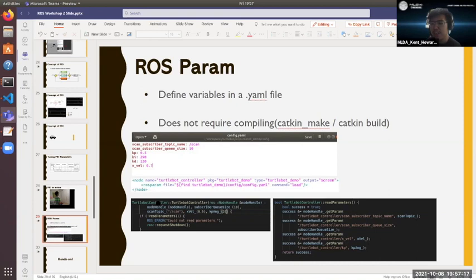First of all is putting the default values. So in case the read param fails, it takes in the default value. Second of all is to kill it. Why do we kill it? Imagine you put your KP controller and it fails to read your KP. Then your robot spins around. Might be somewhat dangerous. So when it fails to get the parameters, you might want to shut down your robot or shut down the whole ROS thing.